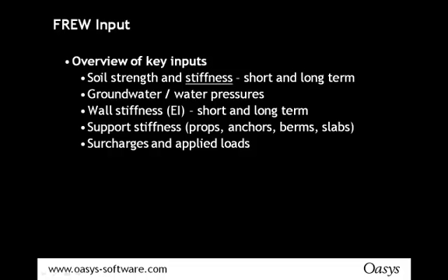The groundwater and water pressure, so what is the groundwater level, what kind of pressures are you applying? The wall stiffness, the EI values in the short and long term. The support stiffnesses, so you have to calculate your props and your anchor stiffnesses. You have to understand your berms and how they're going to affect the problem against slabs. And of course, surcharges and applied loads, what are they, and what stages are they going to go in.